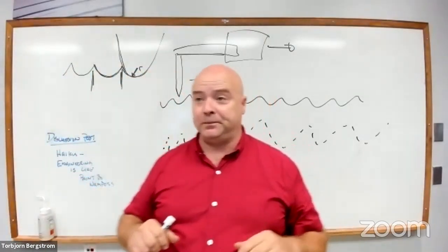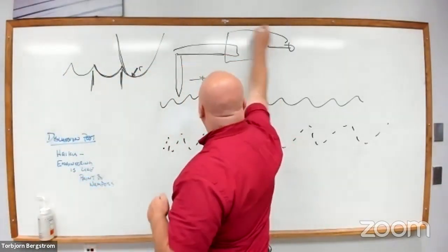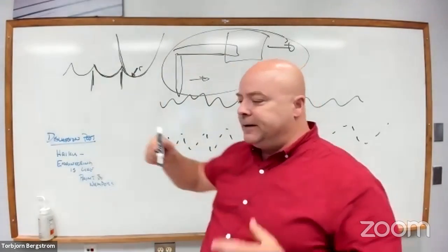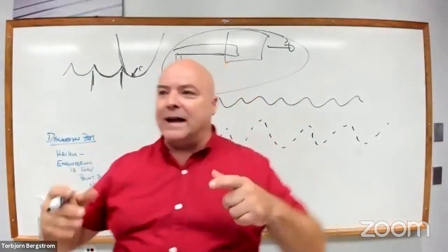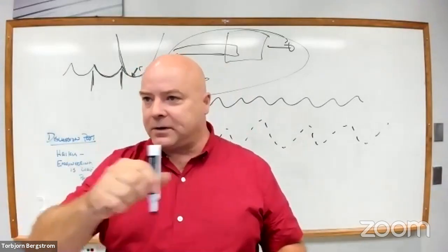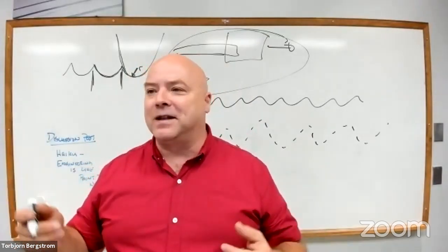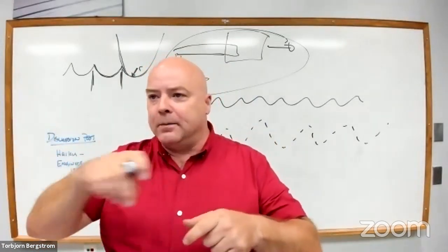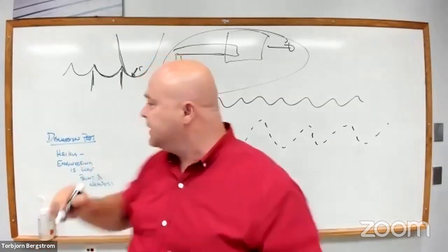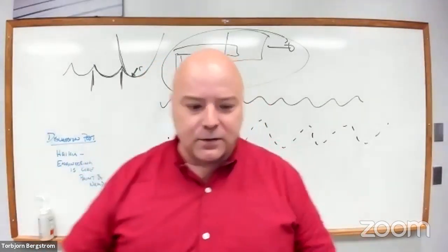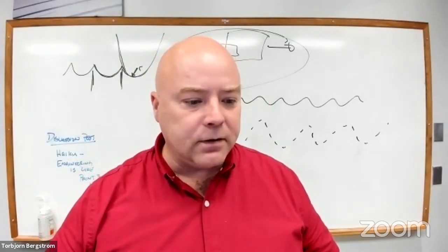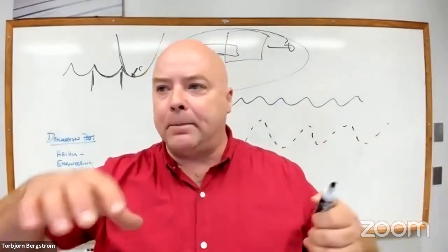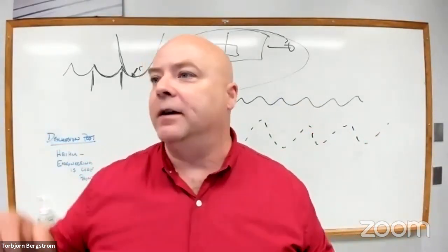That would be slow. So beyond the record player stylus here to measure surfaces and beyond our thumbnail, they have optical microscopes or laser scanning microscopes that can quickly raster scan with a laser height sensor. It's similar to the lasers they use at the barcode readers at the store. It scans across, measures the height, moves over, measures the height, moves over. So this measurement of a surface is really like a 3-dimensional map of a bunch of height values arranged in a grid that we've measured.